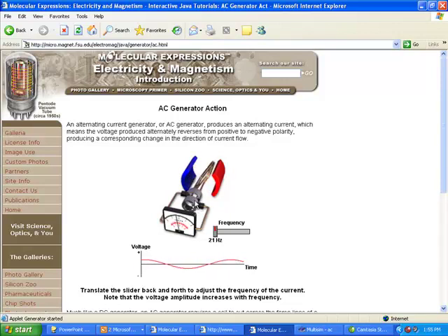And the difference of potential between these two points is what we're seeing on the meter. And so you see this is measuring voltage, and you notice that the voltage is swinging from positive to negative and back and forth. You also see the sine wave that would be generating, and you can see that it is alternating positive to negative, and we have our characteristic sine wave here.